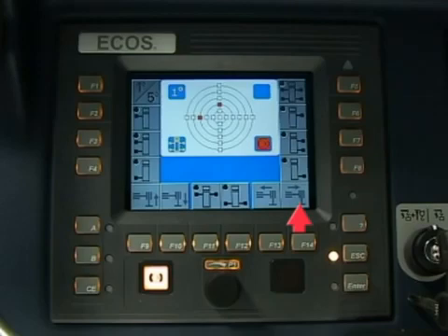For safety reasons, it is only possible to select single outrigger beam functions. When a pre-selection is made, the outrigger beam and cylinder symbols will change from grey to black to indicate the permissible functions. All pre-selection buttons have an indicator light to show the selection is active. The pre-selection is green when active and remains active for approximately 10 seconds to allow a function to be selected.